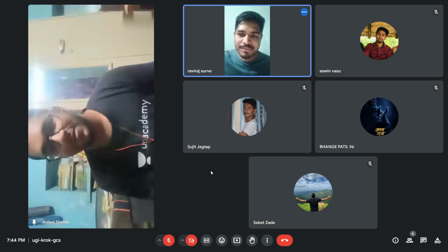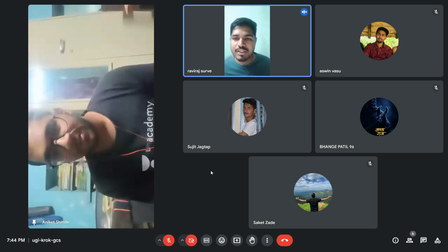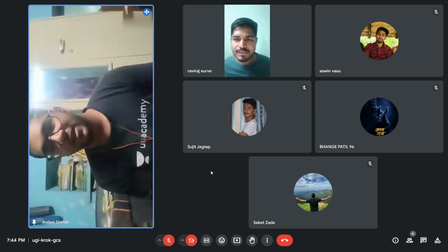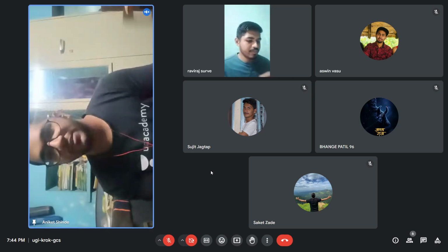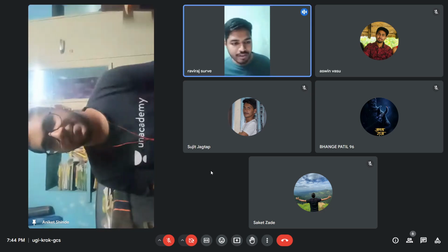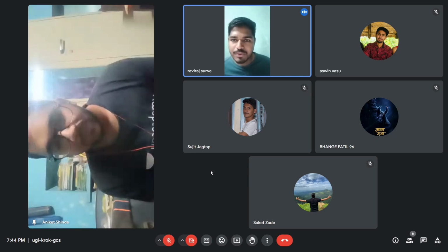Okay. So, Aniket, tell me the function of the flywheel. So flywheel basically absorbs the uneven fluctuations and makes the engine smoother and uniform. Okay. And why do we use a lighter flywheel in two-stroke engine as compared to four-stroke?